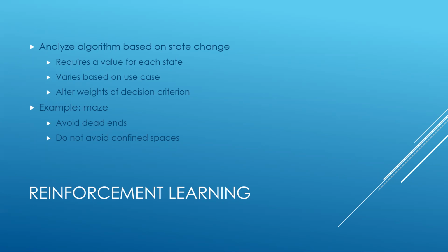For example, if the UAV is traversing an environment designed like a typical maze, the optimal weights would differ in favor of detecting and avoiding dead ends, and penalties for moving into confined spaces of a reasonable size would be reduced. This is reasonable because of the environmental parameters of mazes. They often maintain a relatively constant size along each path, but have many dead ends which the drone may learn to avoid.